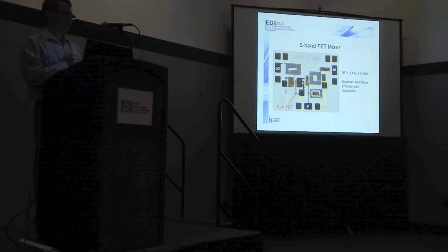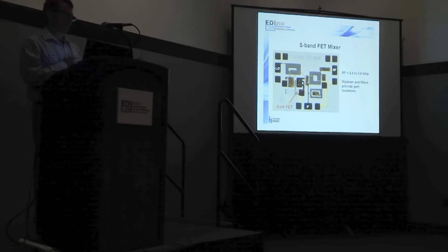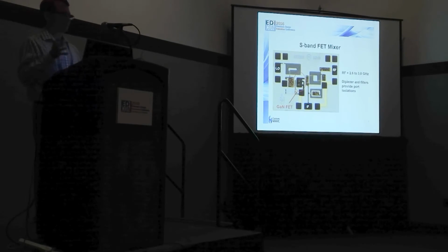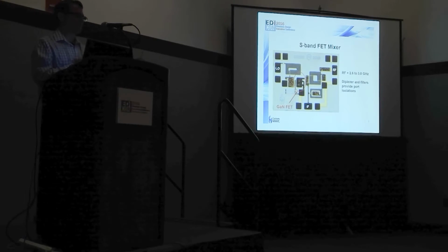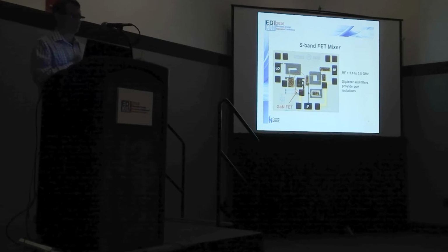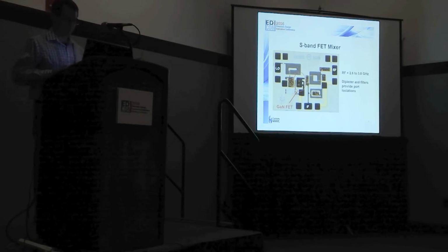So this is not a balanced design. It's just, again, a cold FET with some components around it to massage the performance. And that diplexer and the little band stop filter do provide the isolation of this device.